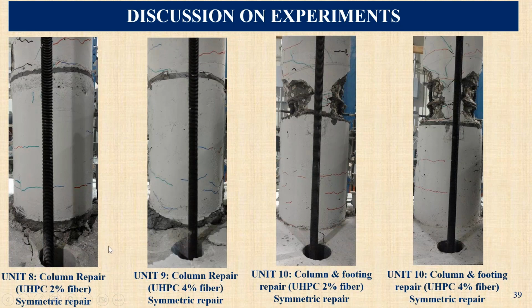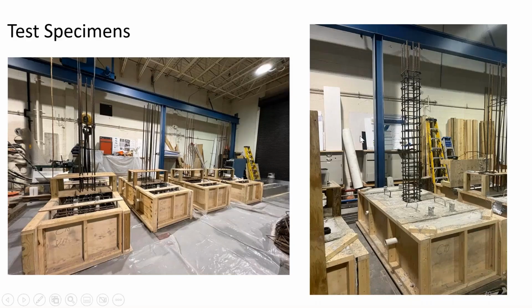Here is what we learned by mistake. Here we saw that the damage was actually in the support. Then we placed the UHPC in the support, and good enough, the damage shifted to above where the UHPC was located.